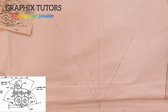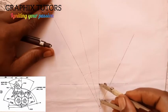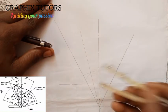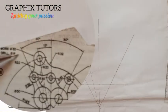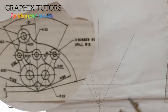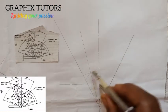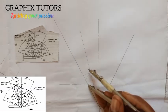All good? So they are meeting here. Now this is when I will take the radius of what? 25. So we know that from here to this point is 25, and also to this point is also 25, right? So I'll place it here, because my circle here is inclined at this 30, and the other one too at this 30. So what I'll simply do is, with that radius of 25, I'll place it here, and where it cuts this inclined line, I'm going to draw my circle.